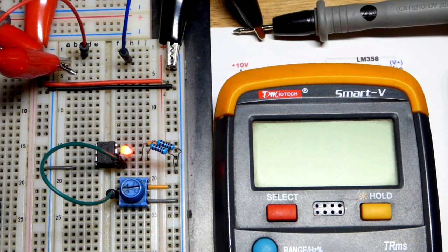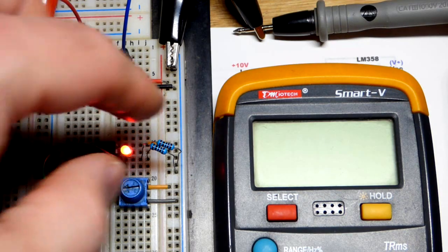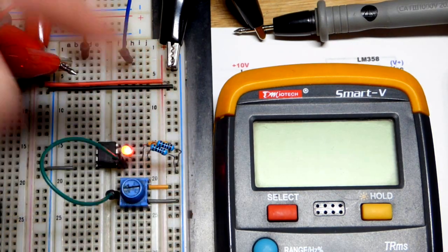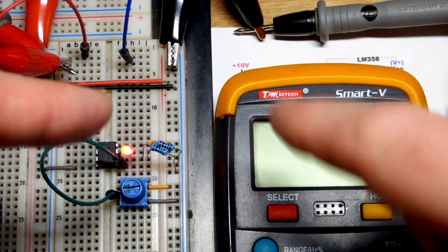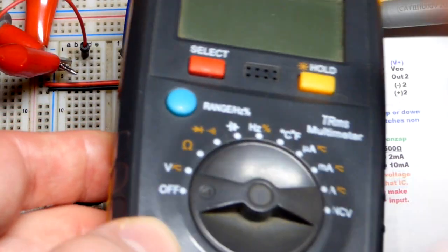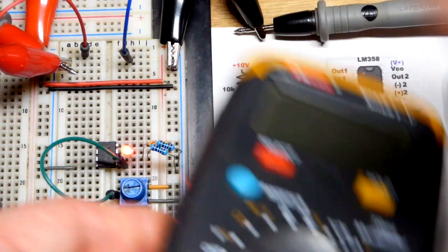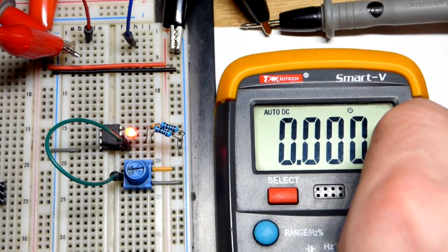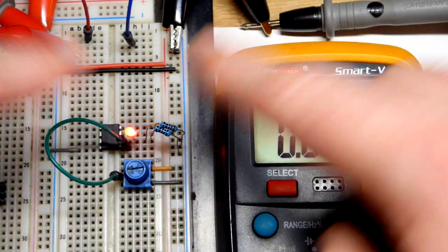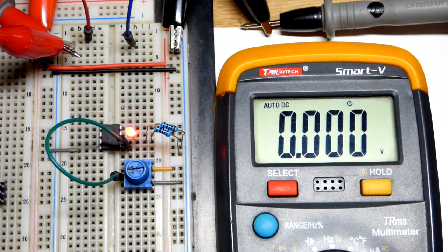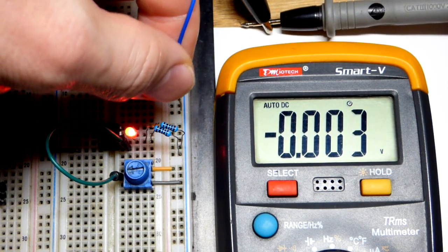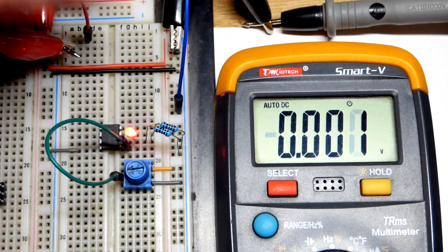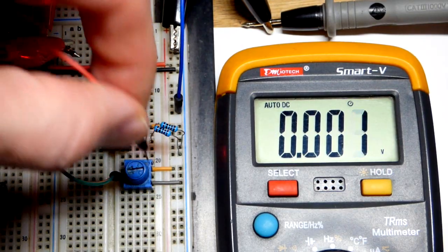So now we're going to go back to looking at the output limitations of the LM358. So we should have about 10 milliamps of current flowing through there. And by the way, I should have unplugged everything before I turned the multimeter off of milliamps. I forgot, and I started turning the dial and realized it still had current flowing through it when I did that. But it probably didn't damage anything. It's a good idea, especially when measuring current, to get it so no current's flowing through it as soon as possible when you're done measuring, because blowing the fuse is the easiest thing you can do to cause damage, and you just have to replace the fuse. Not a huge deal, but it is a pain.